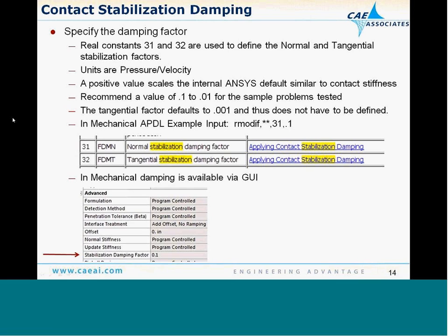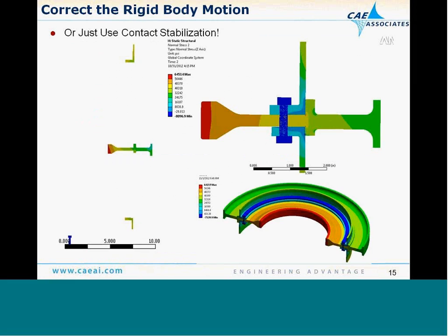I'm sure the option there was that I use all three of those methods, and which one do I use all the time? Well, it depends on the particular project and problem. All three I can concur are typical solutions for overcoming non-convergence. But maybe you'll find in some of your problems in the future that contact stabilization may be an avenue for overcoming non-convergence that works.